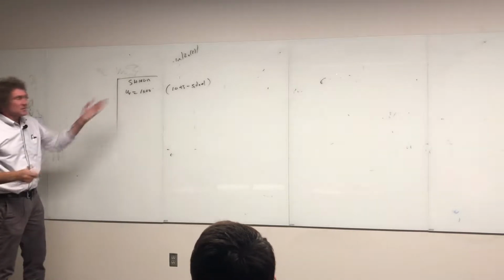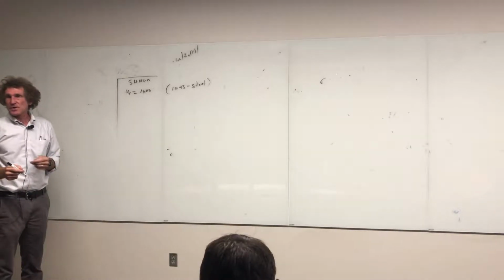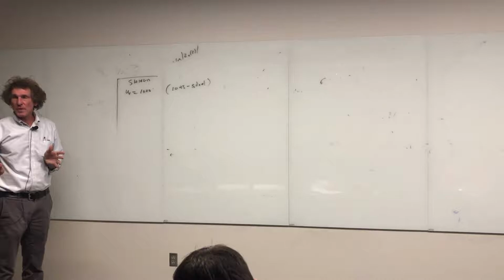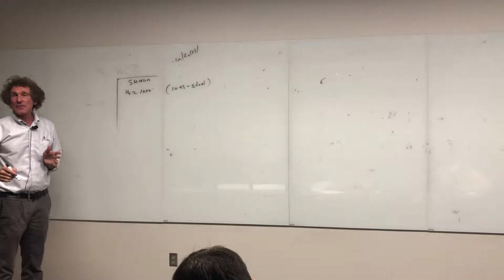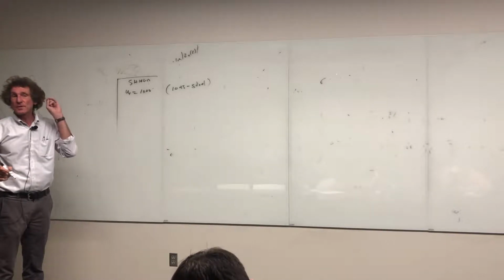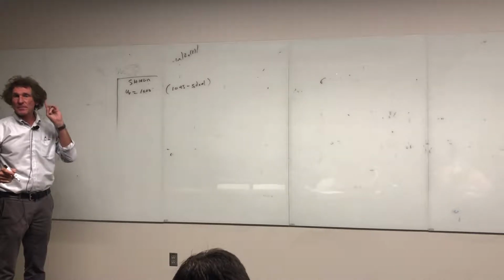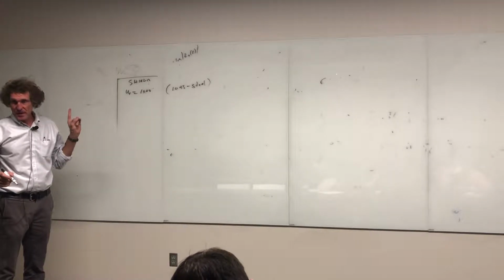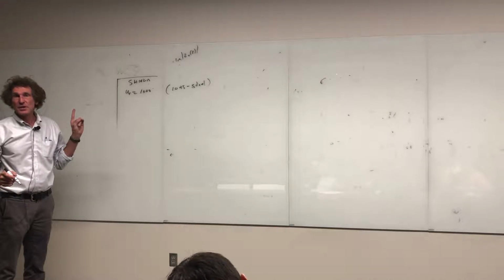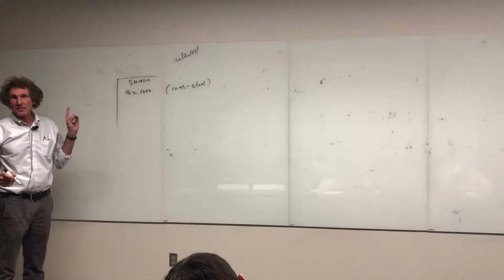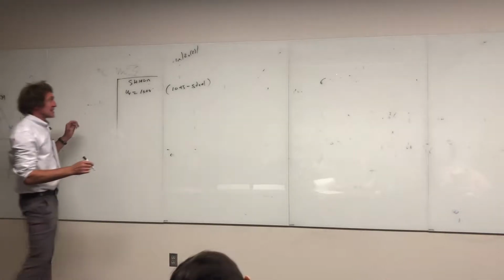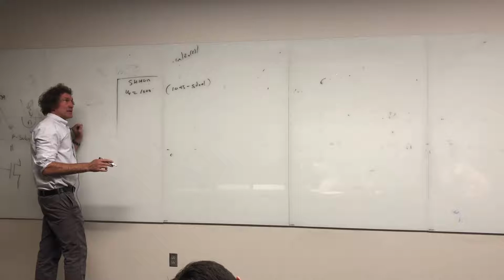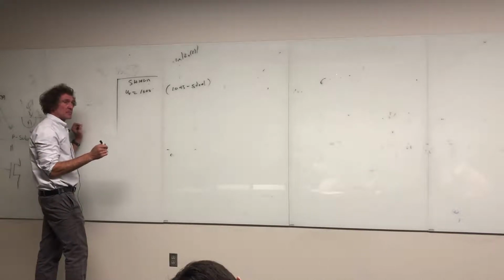Now, this does change versus frequency, but at the frequencies we're talking about, it's about 1,000. Mu relative in the limit as you go to high frequencies always goes to 1 for all materials. Remember that. Mu relative here is 1,000. It's a lower frequency. But mu relative will asymptotically approach 1 for very high frequencies and very large magnetic field values. At least the concept of mu relative will.